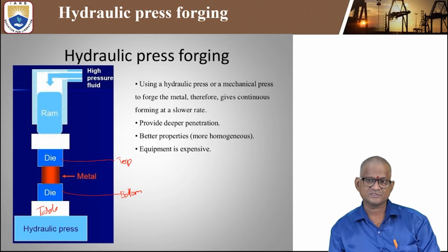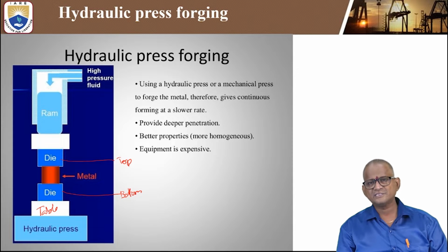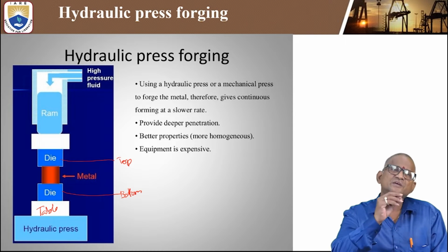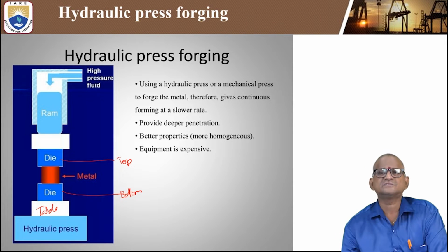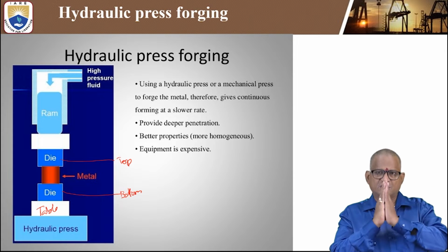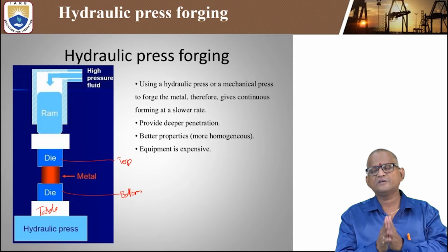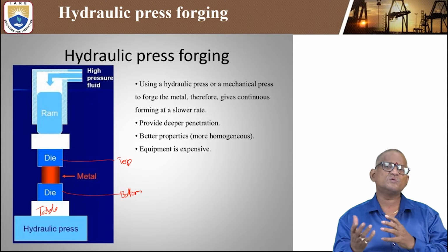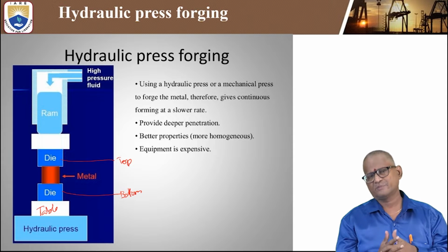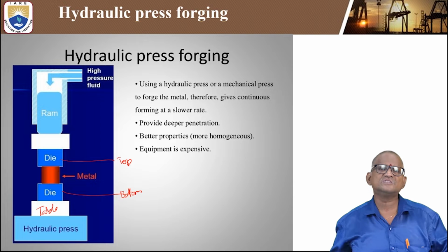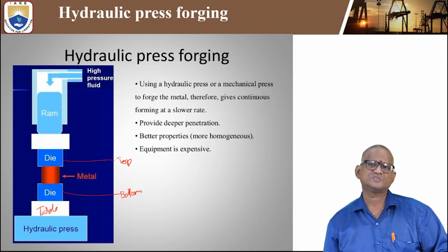In this hydraulic press, you can provide very deep penetration and deeper reduction of the diameter, and the length can be increased. Also, in this hydraulic press forging process, better and more homogeneous properties, whether mechanical, magnetic, or electrical, can be obtained.